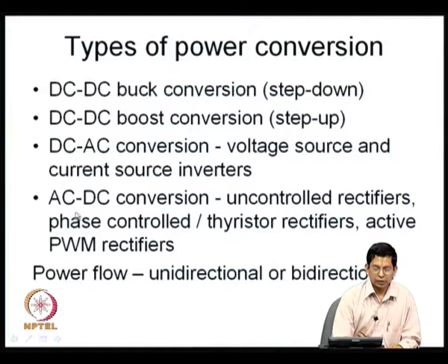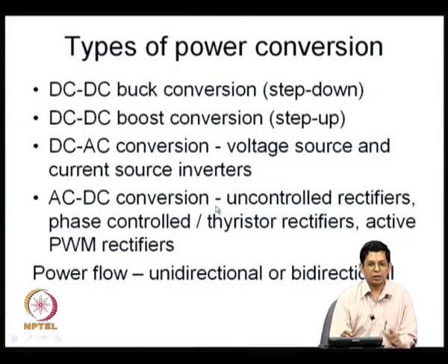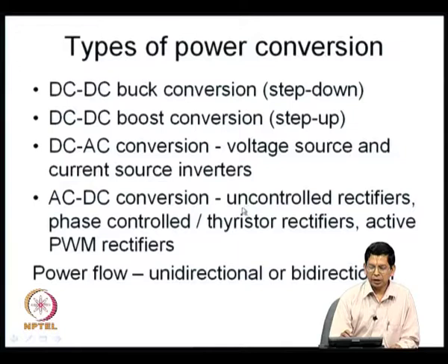Now, there is also AC to DC conversion, which is often called rectification, and the most traditional rectifiers are the uncontrolled rectifiers, basically which use diodes. You can use a single diode for a half wave rectifier, 2 diodes for a full wave, and center tapped transformer. You can use a complete bridge rectifier, and all these I think most of you should be really familiar with uncontrolled rectifiers now. These uncontrolled rectifiers give you a fairly fixed value of DC, except for certain amount of regulation due to loading. They give a fixed value of DC voltage for a given line side voltage.